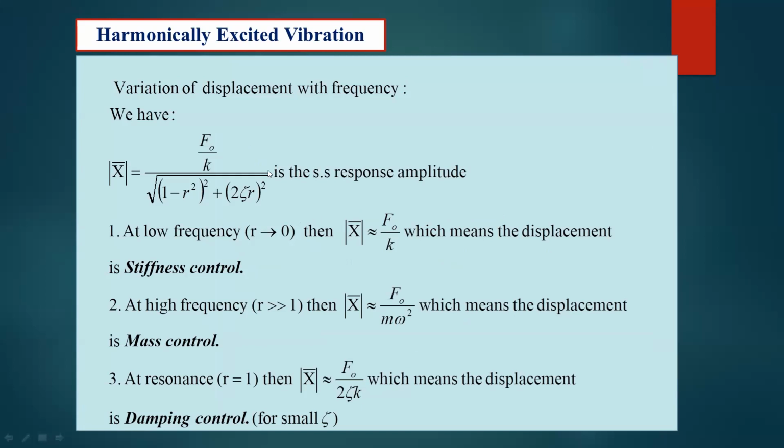So in this equation, just referring to the particular solution, when we are operating at lower frequency, that means r is less than 1, near to 0, our structure should be designed in terms of stiffness control. So we have to provide a material with good stiffness.